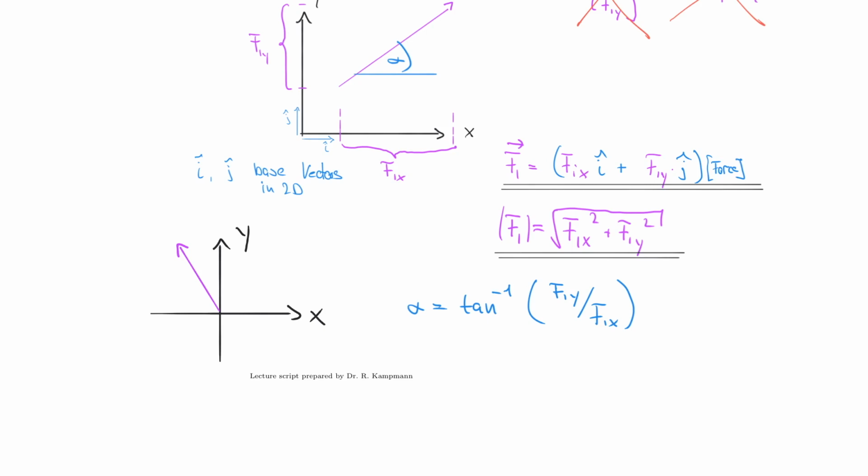You will actually find this angle here. You would find this alpha, because rise over run will give you that enclosed angle. But what's really asked of you at all times is this angle theta. So that is something you need to keep in mind. And again, please be aware that depending on which quadrant you find your resultant in, this will be different and you have to interact differently with that.